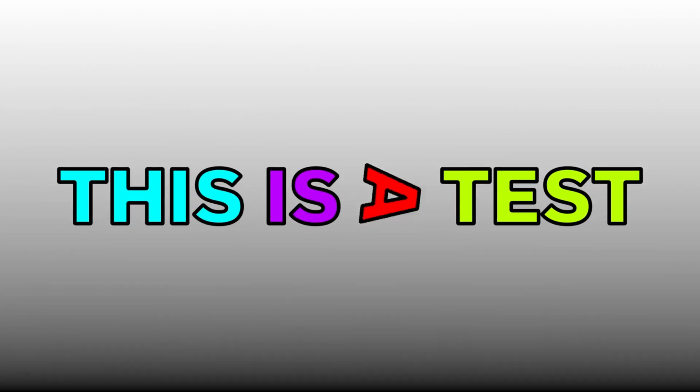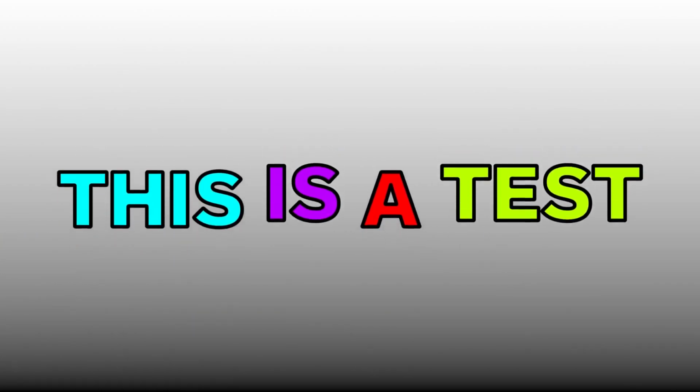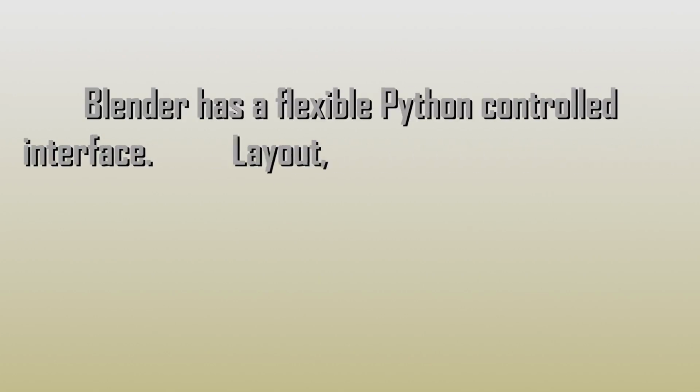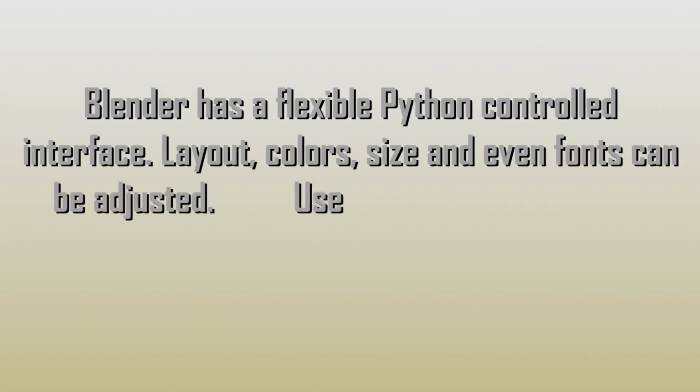Today I'll be showing how to make a node group to allow word-wise text operation with geometry nodes. Currently, as of Blender 4.4, by default we can control text per character using instance index or per line using line index. However, in most Western languages, the smallest meaningful element of a text usually is a word, and not being able to control text animation on word basis is a problem in my opinion.